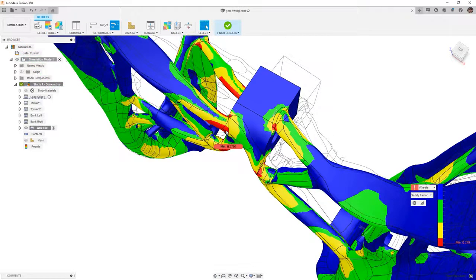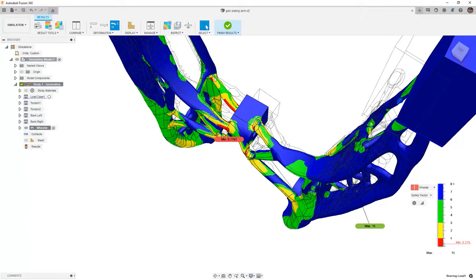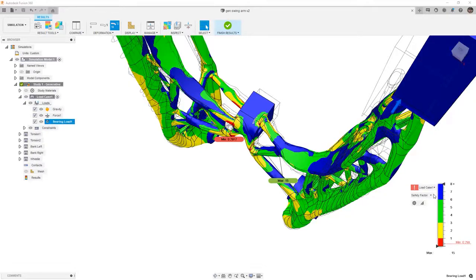This is okay because for this design, ideally we would need to reconnect this to the top, which means that we would need to do a lot of adjustments in this area. This is only for a single load case, and the wheelie load case is where we have the maximum load pushing forward. Let's go ahead and take a look at load case 1. The factor of safety is a little bit higher, and this was the max compression. You'll notice that it's 0.298.